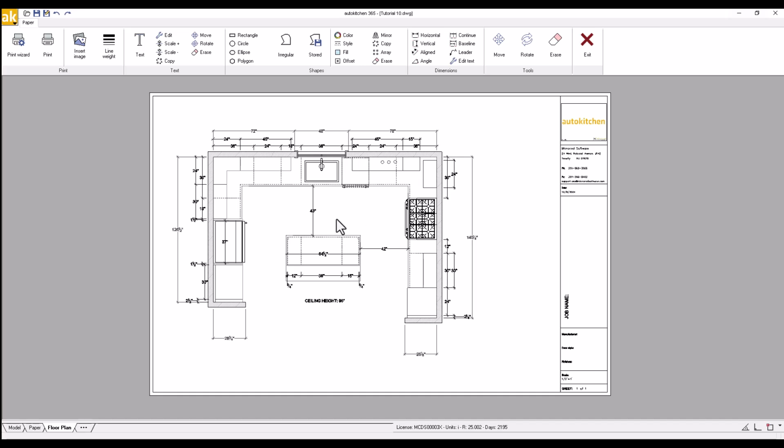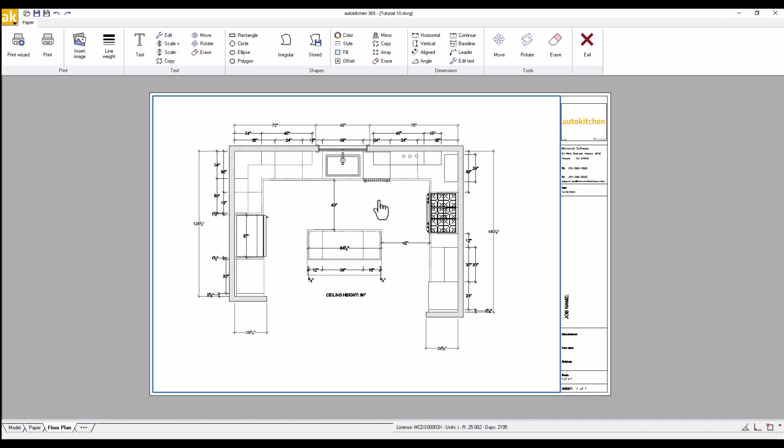The plan is likely to be centered on the page. If the plan is not centered, double-click in the center of the plan, then press and hold down the mouse wheel and pan the view until it looks centered. Try not to roll the wheel while panning, as this will change the scale. Once centered, double-click on the gray space to the sides.